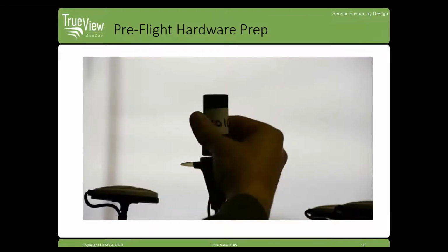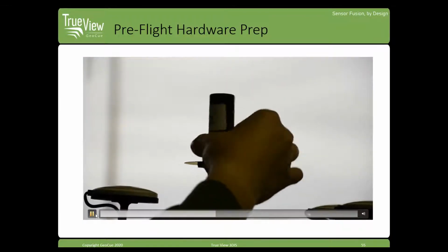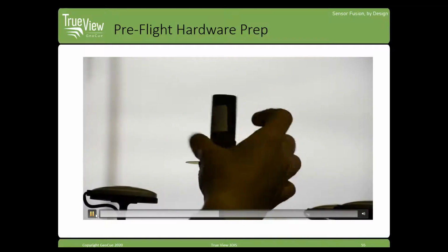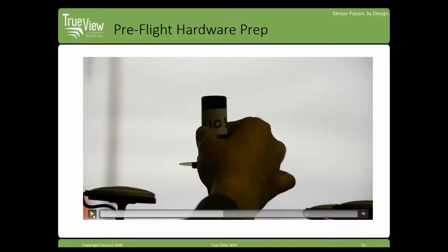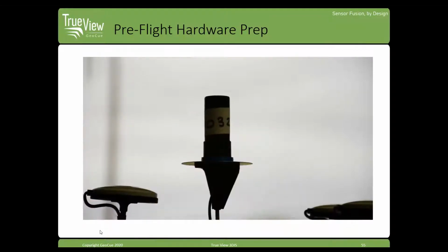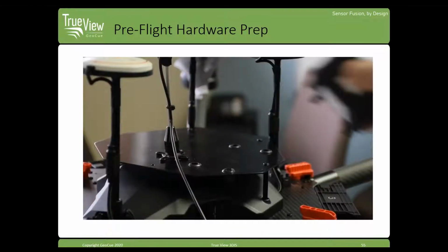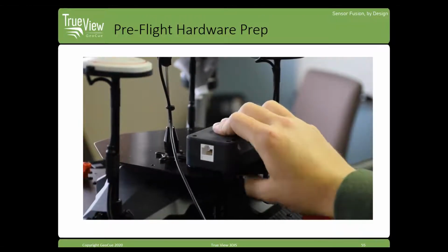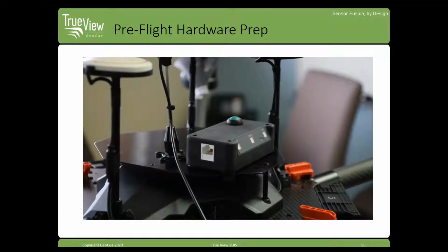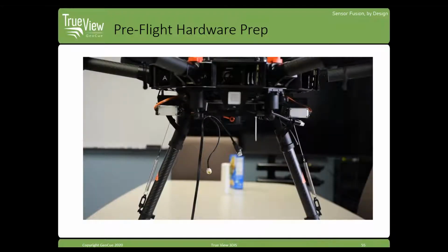You'll screw on the antenna. You want to make sure this is on there pretty snug. There is a spacer built into the antenna mast that is compressible, so you're not going to hurt the antenna or the mast by screwing it in pretty tight. You don't have to get it too tight, of course, but you want it on there pretty good. You'll next put your control box on the top plate here. This is the older style, but it is pretty much the same.